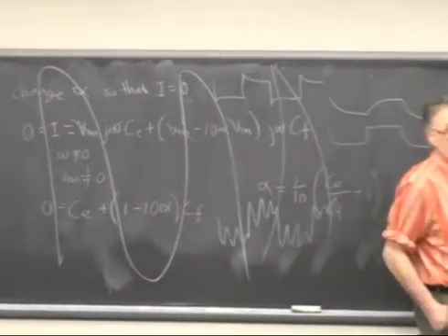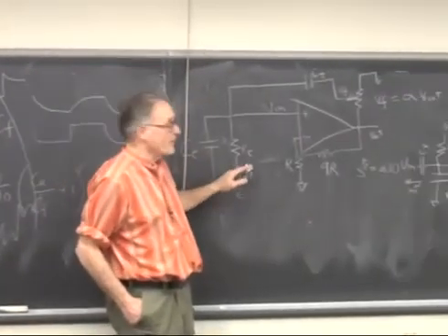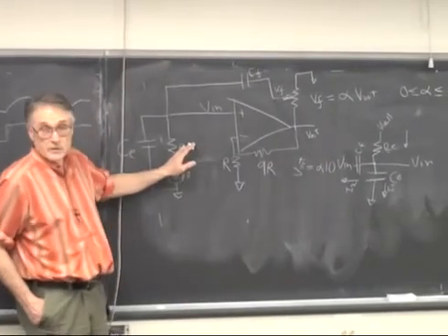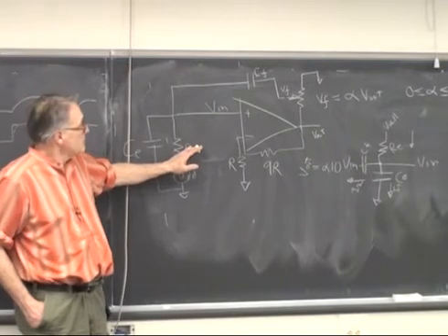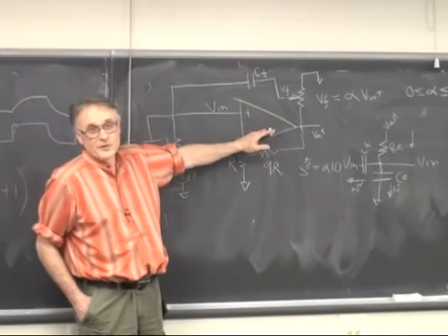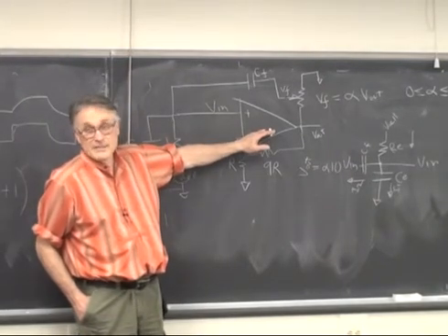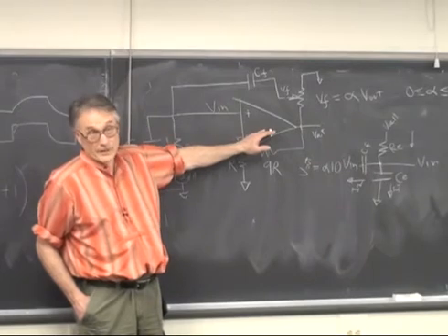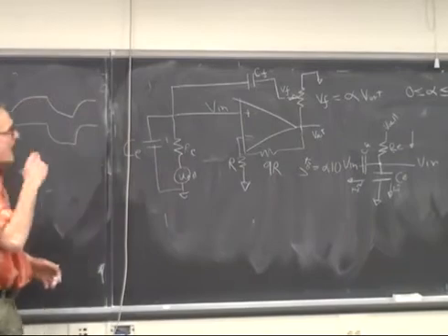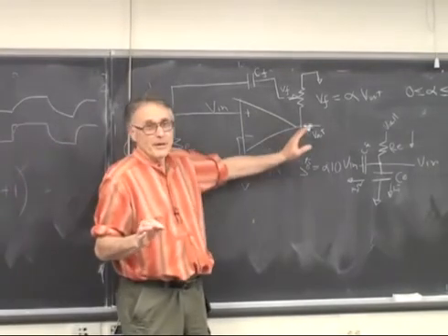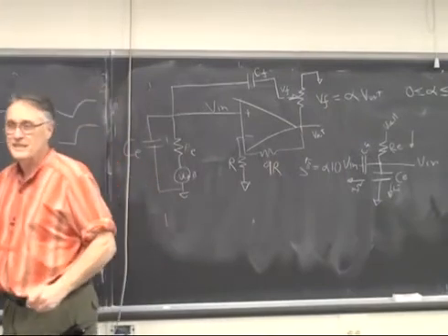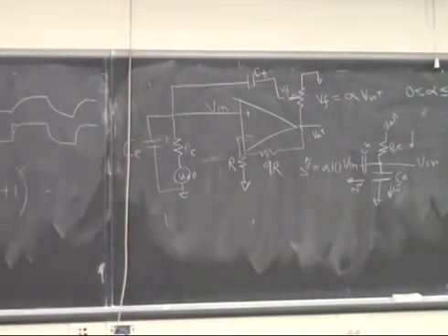Secondly, it's worse than that. It's worse than just amplifying the thermal noise from this resistor, and all resistors have thermal noise. You amplify the internal noise of the op-amp itself quite considerably at high frequency. And the transport delay through the op-amp itself becomes highly significant and destabilizes the system.